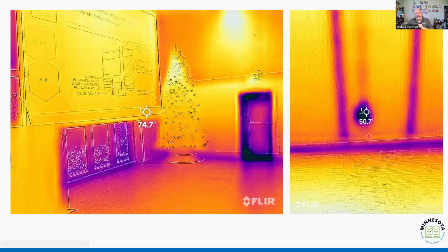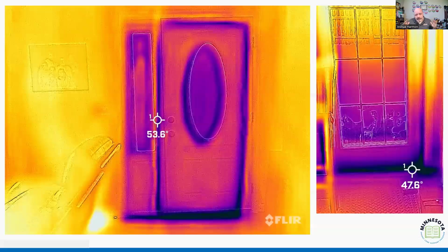And these are the things that, again, with a little bit of air leakage, we can walk around with a thermal camera and say, oh wait, we've got some air leakage here. How are we going to address that? We're going to seal it. Same thing when we see that exit door, right? This was not a traditional normal exit door, but it is going to be something that we're going to have air movement going through. I know we don't always talk about residential, but again, residential has similar expectations. When that door is not properly sealed, we can see the difference. We can see the impacts, right?